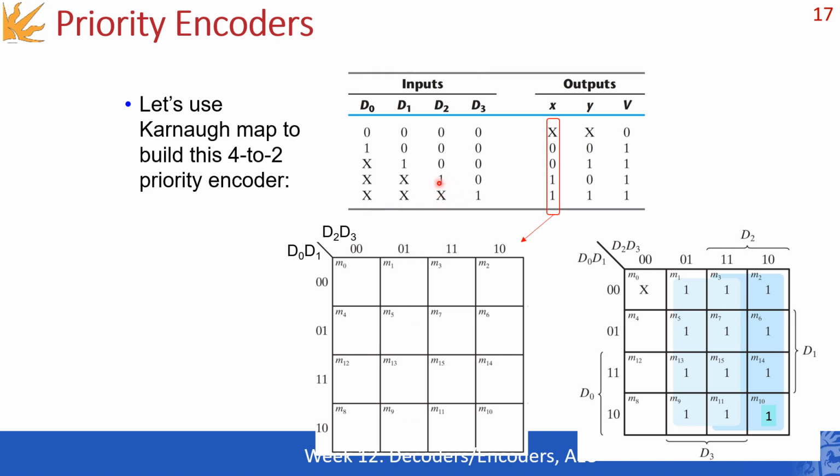As for here, you got 2 bits, which means another 4 combinations. So overall, you are expecting to have 8 plus 4, 12 min terms. And indeed, if you put all the min terms here from the complete truth table, if we expand everything that you have here, it will look like that.